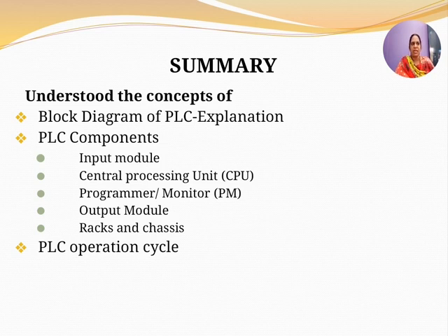The input devices and the sensors may be a push button switch or a liquid level switch, or it may be a limit switch or a pressure switch. The output devices may be a motor or a solenoid or a speaker or a light or a bulb which glows. So the major units of a PLC section are the input module, the central processing unit or the CPU, the programmer or the monitor, the output module, the racks and the chassis, the PLC racks and the chassis.